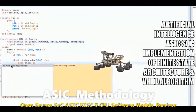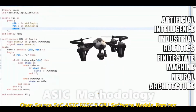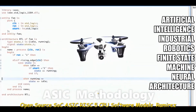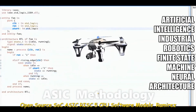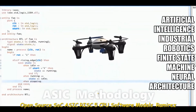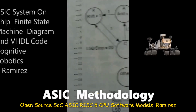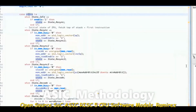Using the state signal, the finite state machine, the case statement contains a when statement for each of the possible states, causing the program to take different paths for every state. The when statement can also contain code which should be executed while in that particular state. The state will then typically change when a predefined condition is met.